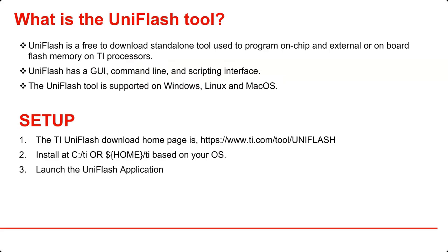The tool can be set up in 3 easy steps. First, go to the TI Uniflash download homepage and get the tool. Then, based on your operating system, download and install it in your TI directory. Then launch the Uniflash tool.